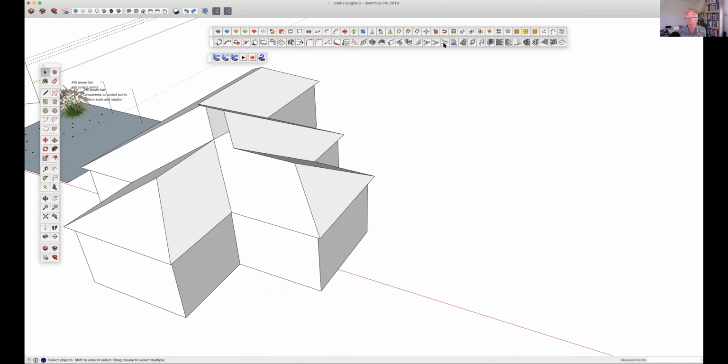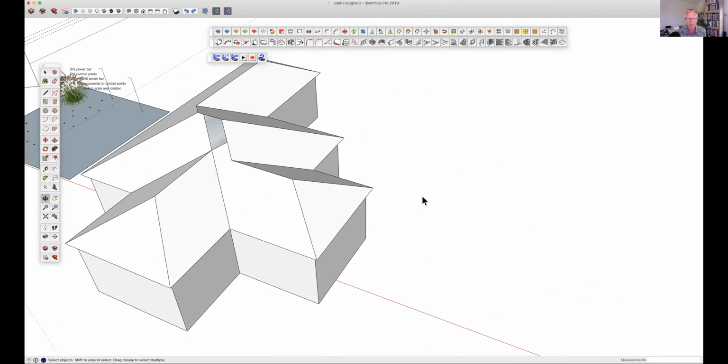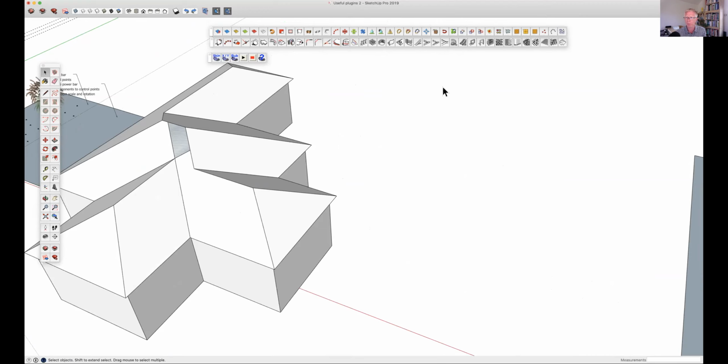I keep trying this set from 1001-bit because there are several things in here that are really useful. And one of them is an automatic stair flight generator. And you can see the little icon, hopefully, in the center. And there are 5 icons, in fact. One's a simple set of steps. And then we've got other ones which will create flights between stories. So we get dog legs on our steps. And right at the end is a spiral staircase. So just figuring out these with native tools in SketchUp would take time, and it will do it almost instantly.